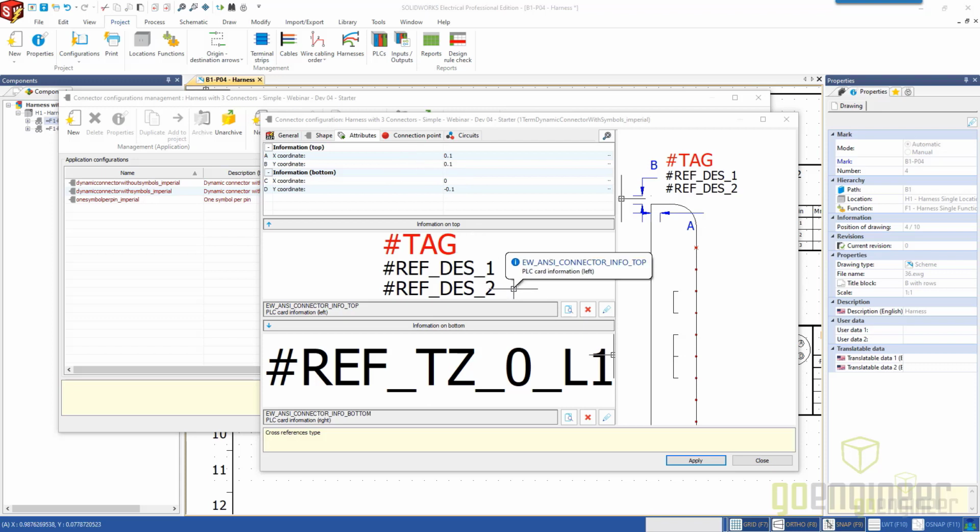So these are files that you can edit. My recommendation is go into Library, Symbols Manager, and copy the existing one. So find where that one is in the library, copy it, modify the copy, come back in here and search for that modified version of it, just so you can do your own thing as far as that information goes.